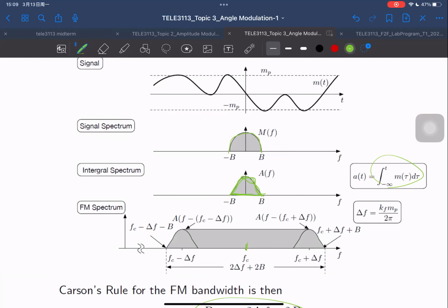Got a question for that? Is that because they're all cos? Yeah, they're all cos terms, so you don't have to do anything. Also, there's no imaginary section, right? Because if the given signal were a sine, then you would have 1/2j delta f minus f naught and some stuff, and you get an imaginary term which causes a phase difference.